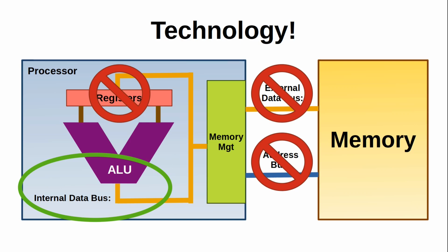And so that's what we're going to look at: CPUs that have an internal data bus that's 16 bits, and along for the ride is a 16-bit ALU, so it can do direct operations on 16-bit data. So you could have two 16-bit registers, and you're doing a 16-bit add, say, within that ALU. Because like you can see from the Z80 videos, yes, you do have 16-bit registers. You could add BC to HL and do a 16-bit addition in a single instruction.